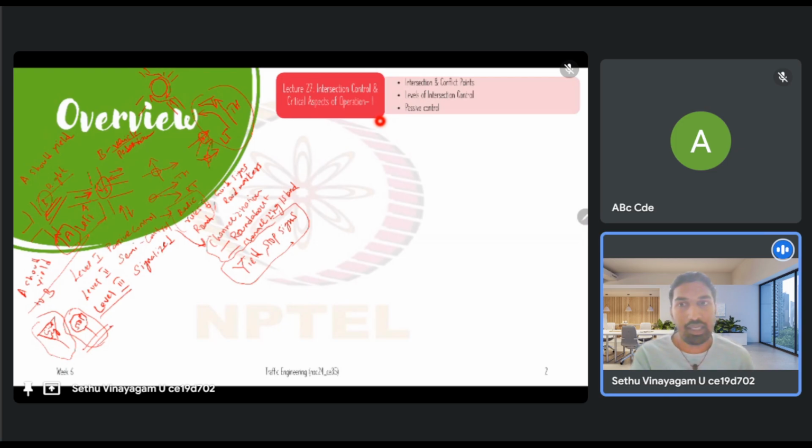How are we doing it? We are separating the traffic in a temporal way, which means that in a cycle, when one approach gets green, movement will happen here, and the movement in the other approaches will be stopped. Then after some time, when green comes to another approach, the movement will happen there, and the movement will be stopped in all the other approaches. So we are providing the right of way to different traffic movements by separating them in a temporal manner. At different times, different approaches get the right of way. That is explicitly altered by using these traffic control devices.